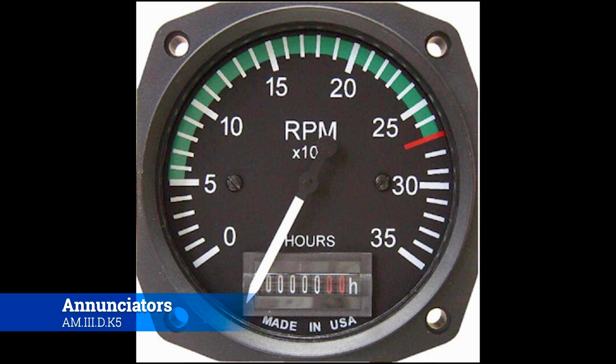At 2,000 RPMs, that's where you're going to do your magneto checks. Whenever we go to check the magneto and it drops down so many RPMs, there's a differential, usually like 175 max and then 50 between. That is going to be done at about 2,000 or so.